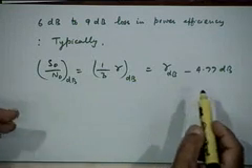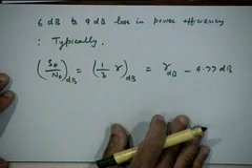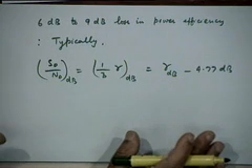This power efficiency that we have calculated, the output SNR, is for the situation where the demodulation is synchronous. But actually we transmit carrier so as to get simplicity of demodulation, not to have to use synchronous demodulation. So, the next question is, would the envelope detector give you the same performance as the synchronous, the coherent detector does? That is the next question that we need to look at.